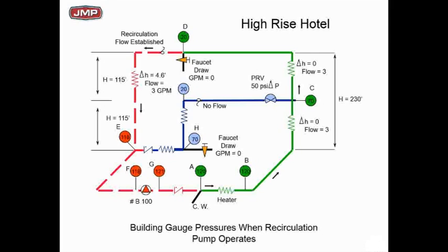Do you see where the 70 pounds blue is? Going through a check valve into the red. So you telling me that 70 pounds will not flow into 118? No, I don't think it will. I don't think that recirc pump of 70 pounds is going to flow into the 118 down to the recirc pump. So the top 10 floors are recirculating nicely.